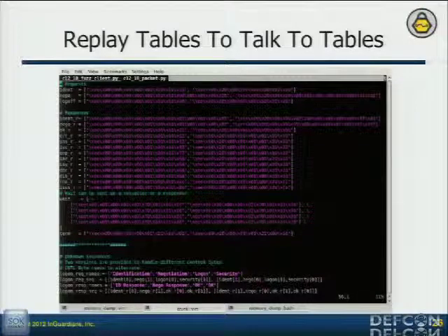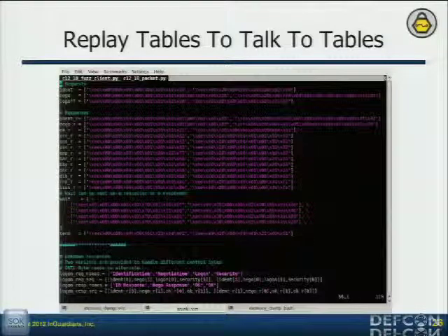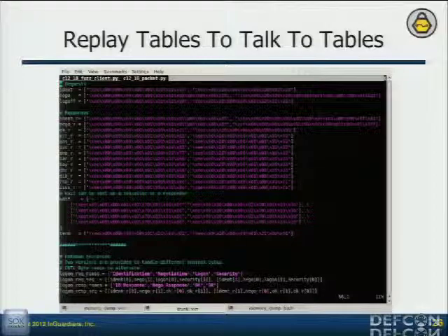And as I'm writing that, and I'm looking at it, I'm like, wait a minute. When I was working with Atlas, working on the MSP430 disassembler and emulator, he told me, when you're working with Python, tables are the best way. Tables are the fastest things to reference. I'm like, holy shit, I've got tables. Because every response and request is exactly the same. I mean, there's a slight difference. There's a control byte, but I can account for that. It's exactly the same. So I can just write tables of tables. And if I can write the tables of the communications, I know what's coming back. Now I can start generating my tools.